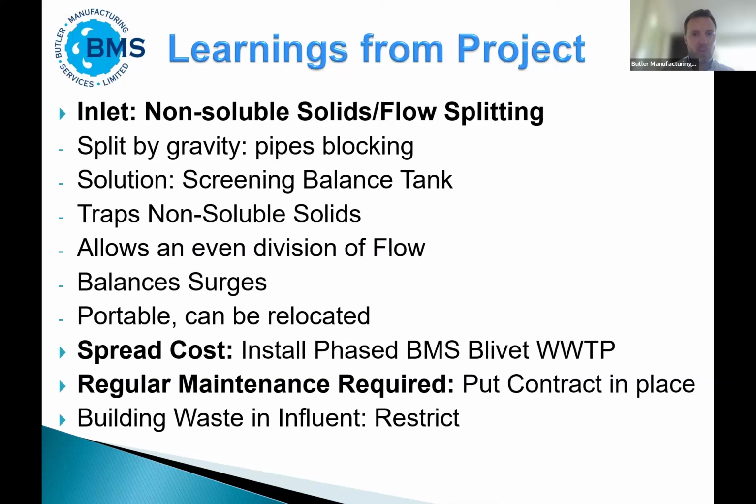So learnings from the project, there's always learnings from every project. We've experienced a lot of things in our 40 years, but we don't know everything. And every project always has unique challenges. So on this site in particular, we had a big problem with non-soluble solids, tampons, baby wipes, rags, and everything coming down. The fact that these are state provided houses means, with no disparaging on the residents, that it tends to be more non-soluble solids